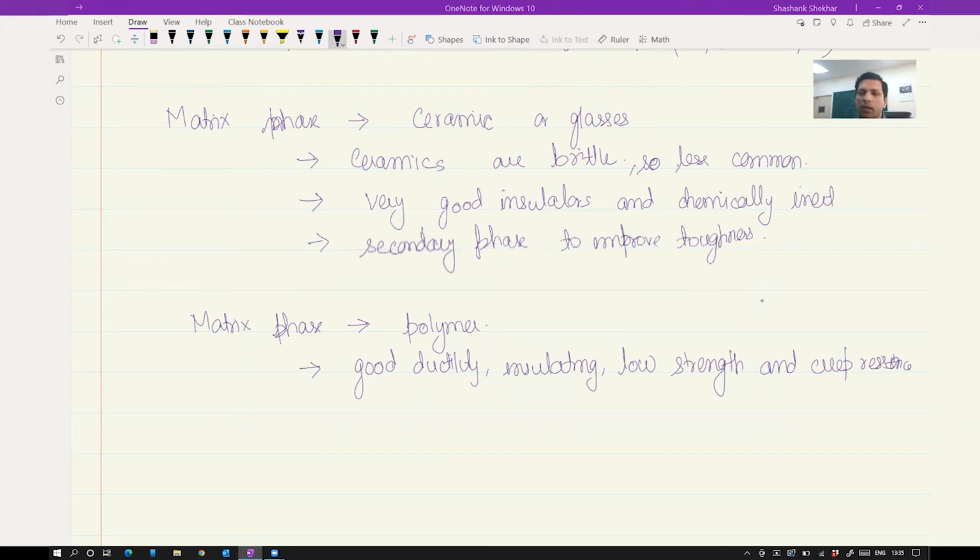If you look at the older type of wires which were used, you would see that the aluminum or the copper were much thicker, because over there the purpose was not only conductivity but also to provide the overall strength. But nowadays, to reduce the cost, manufacturing has been optimized so that polymer is the primary load carrying component.